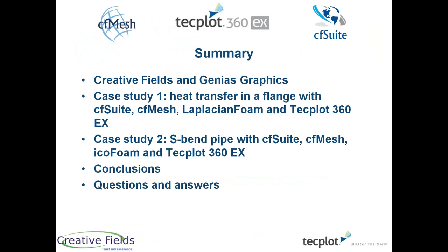So today's summary: a brief introduction about Creative Fields and Genius Graphics, and then we will present some examples of workflow from data that is issued from tutorials from OpenFOAM. The first case study will be heat transfer in a flange. Meshing and solving will be made with cfMesh and Laplacian foam, and visualization with Tecplot 360EX.